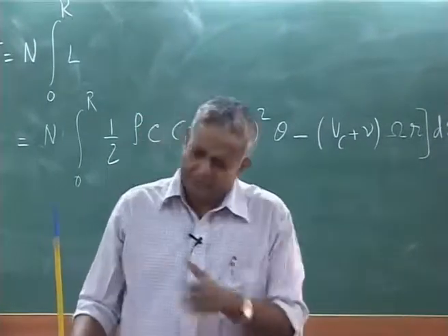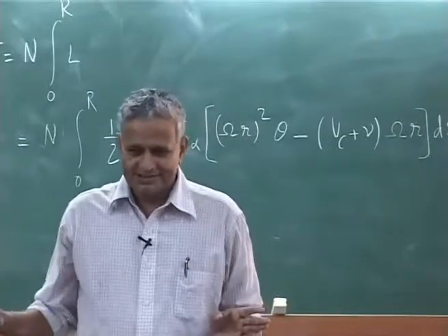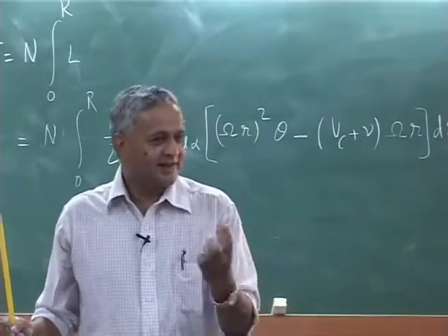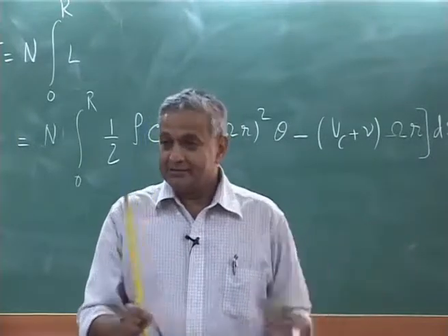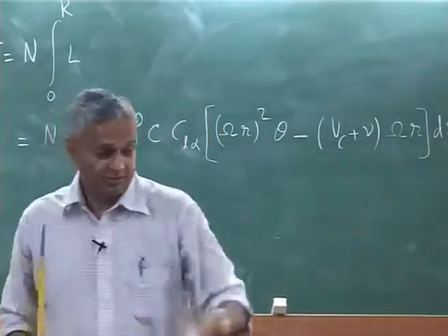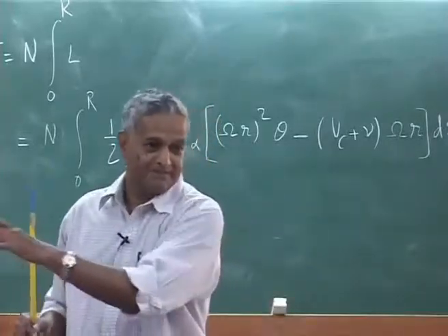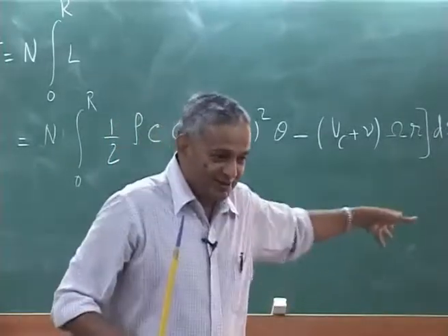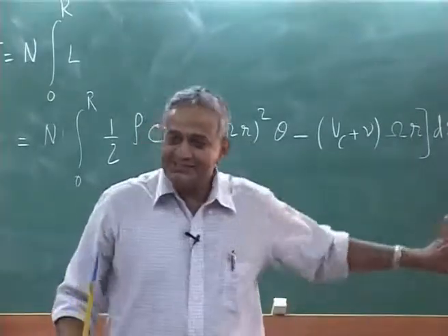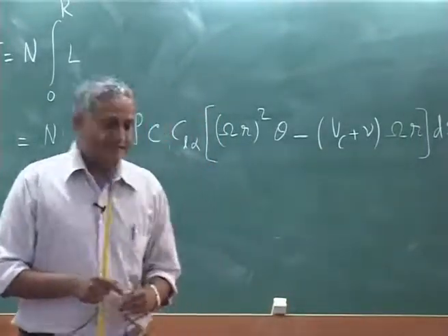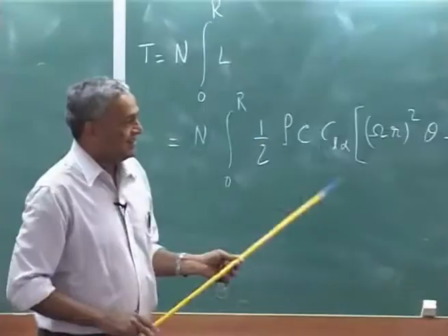But today most of the rotor blades have a constant chord except near the root. Otherwise, your chord can vary, so you cannot use the same expression, you have to put that integration. But normally what is done is we take some constant chord and then we calculate.